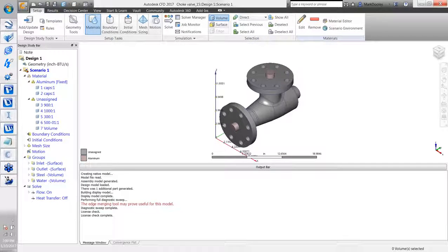So as we are launching our software, we've already created the design here, so we don't have to add or bring anything in. We do have templates that we could set up and rules that we can map materials to and so forth. So when we're bringing a model in from Inventor, we want aluminum to automatically map to the aluminum library, or steel to go to the steel 303, 404, aluminum 6061, whatever it is. We can have those rules set up and in place to where they automatically map. In this case here, I'm not using those. The aluminum did come forward, but the other materials did not.